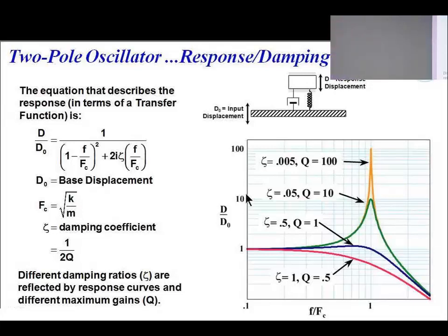But the point here is that our structural response is going to be very heavily dependent on the damping, this damper right here. If the damping is low, then I'm going to get a lot of response at the resonant frequency. If the damping is high, I'm going to get a very mushy response. And one of the things that we talked about, and we'll talk about again, is the damped accelerometers that Best and some of the rest of you guys are using, strain gauge accelerometers, and they are designed,